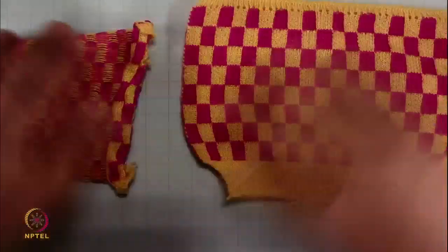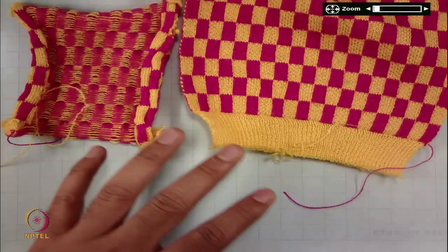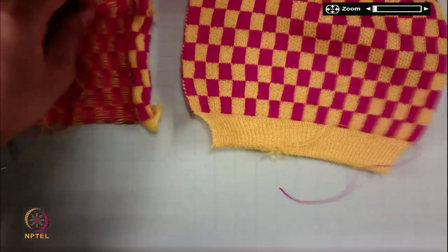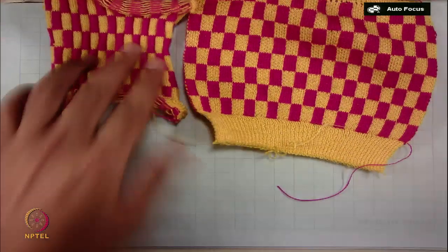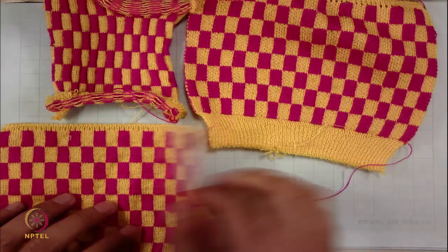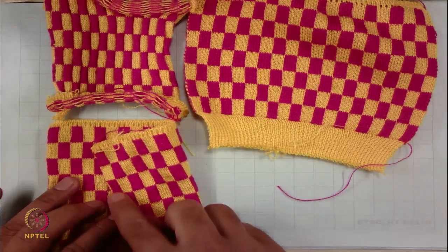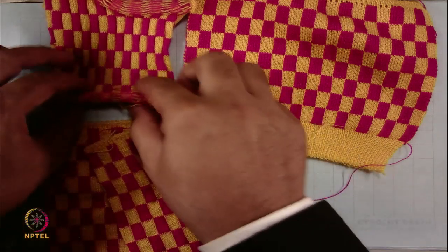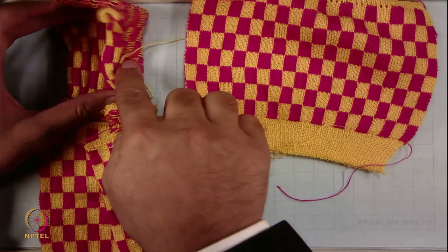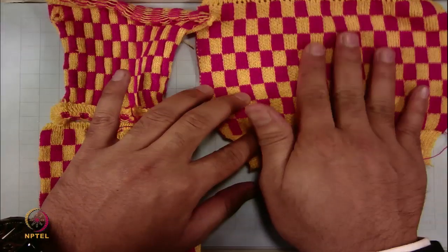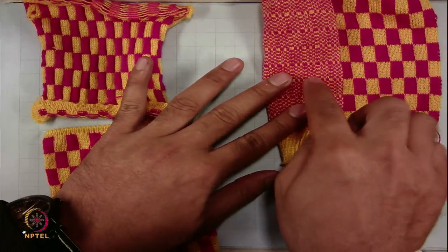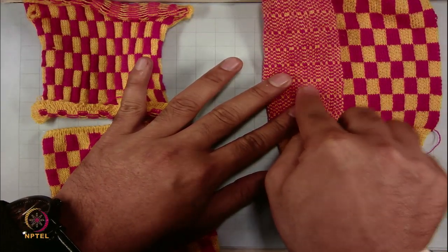And this is the tubular jacquard. I am putting all types of jacquard in one place so that you get a better understanding and differentiation of all three types of jacquard. So, this is tubular jacquard, which looks the same on both sides. This is float jacquard, one side loop, other side float. Third is bird eye jacquard, one side loops, other side a combination of float and back loops.